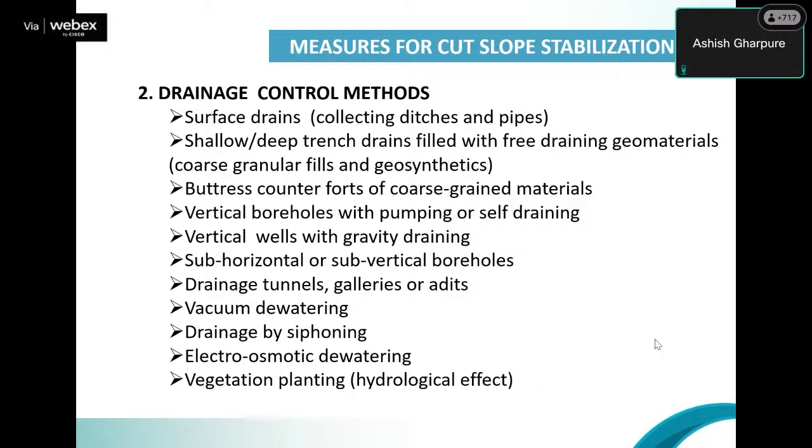Now, coming to the most important part of any slope stabilization, which is drainage control measure. It's so important that I don't mind repeating it several times in this presentation: if there is something to be highlighted about any slope stabilization, it is drainage.